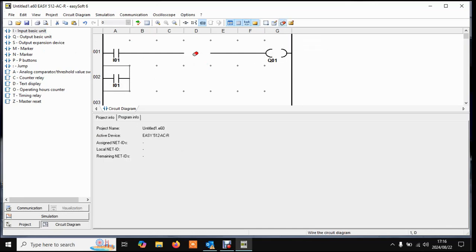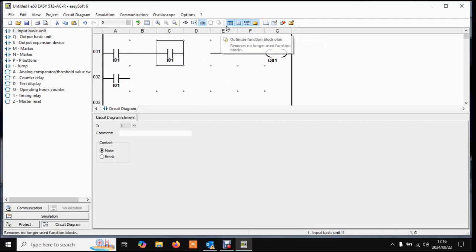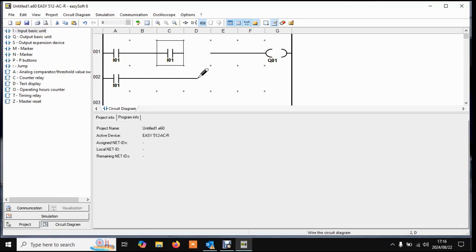So we can erase here maybe and put another switch. Right, there's a switch there, and now by dragging and dropping it, we're going to look for the pin. There's the pin. It says draw connections, so click the pin, and now we're going to draw by left clicking the connection. And so you can see this is not really a latching circuit, so you can click erase over here, delete, and you can clear that up. Click erase again, switch to the pin, and you can draw, and now you have a latching diagram.